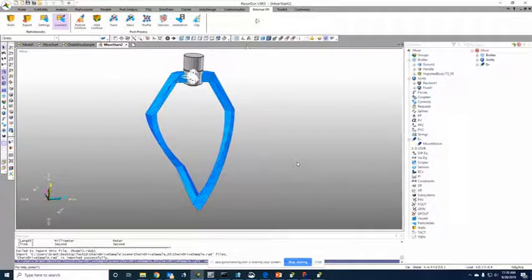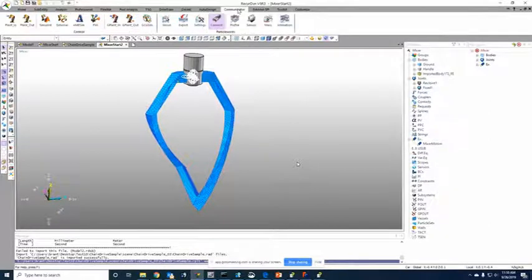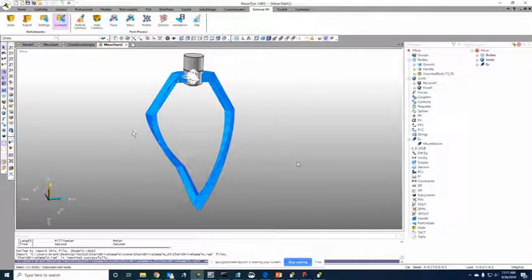There is the older communicator tab, which you may have up there as well, and that does have a Particleworks interface. That is a little bit older, and you can't do co-simulation including the flexible bodies with this older interface. So it's the newer external SPI interface that you'll want to be using.